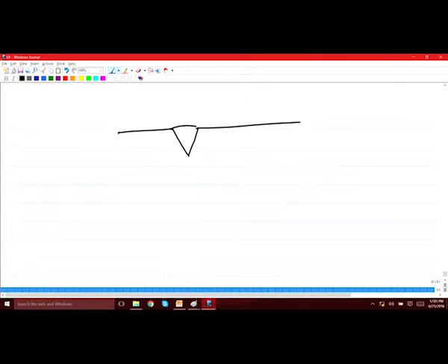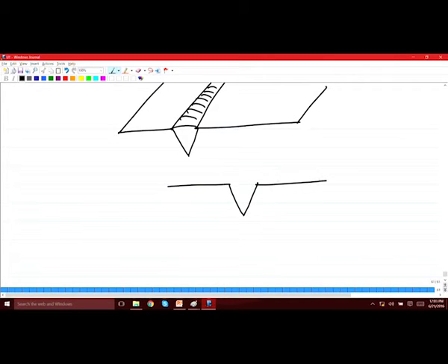So, this is the weld, and if you see the view, across this interface, these two plates are joined. Okay. So, this will be the weld. Okay. So, in this case, as you would have realized, you cannot use a normal probe, because in that case it will simply go like this. Even if you keep it on the top of this, there are these surfaces, the welding joint is here. So, it is not appropriate to use a normal probe in this case.